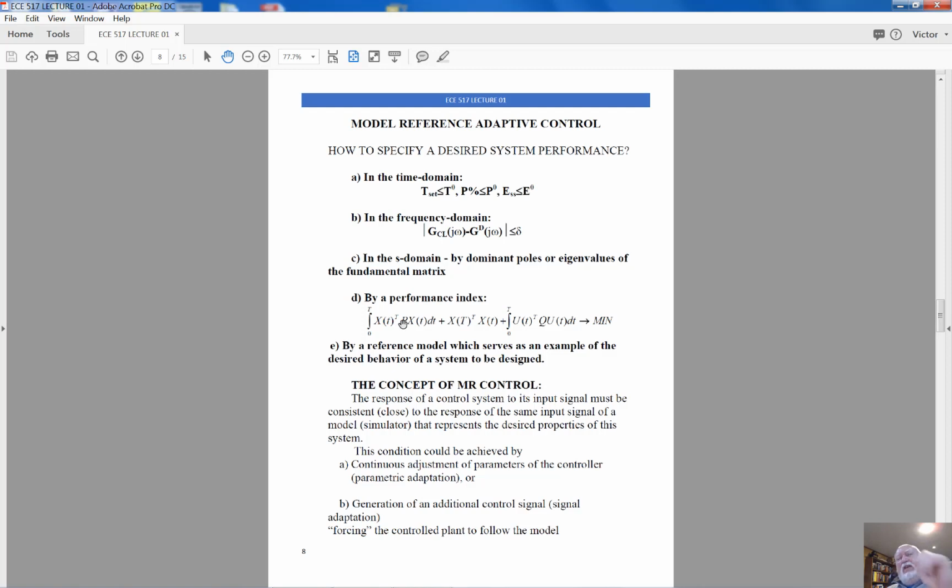And P is the matrix that defines the penalty for specific trajectories within the state space. The second term does not have integration, but this term is responsible for the final state of the system at the end of the settling time, because this term effectively represents the steady state error.